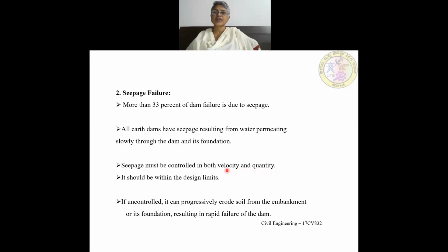If the velocity is more, it will carry the materials along with the seepage water, causing cavities within the dam. It should be within the design limits, and if uncontrolled, it can progressively erode the soil from the embankment or its foundation, resulting in rapid failure of the dam.